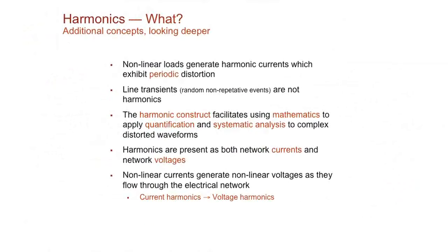What causes harmonics? Who's the generating cause of harmonics? Well, any nonlinear load causes harmonics. Examples of those are non-incandescent lighting, computers, copying machines, battery chargers. Anything that takes AC power in and converts it to DC is a nonlinear load. So number one, the biggest loading of that is probably these guys, right? Drives, VFDs. Even these lights above our head are nonlinear loads. They're causing harmonics in the system.